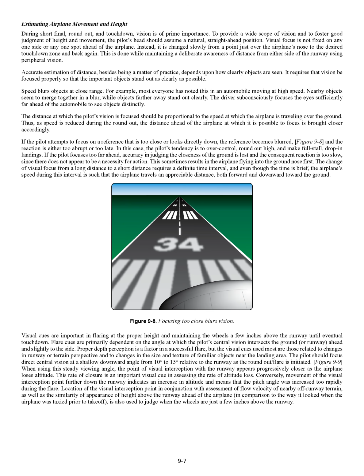If the pilot attempts to focus on a reference that is too close or looks directly down, the reference becomes blurred, and the reaction is either too abrupt or too late. In this case, the pilot's tendency is to over-control, round out high, and make full stall, drop-in landings. If the pilot focuses too far ahead, accuracy in judging the closeness of the ground is lost and the consequent reaction is too slow, since there does not appear to be a necessity for action. This sometimes results in the airplane flying into the ground nose first.